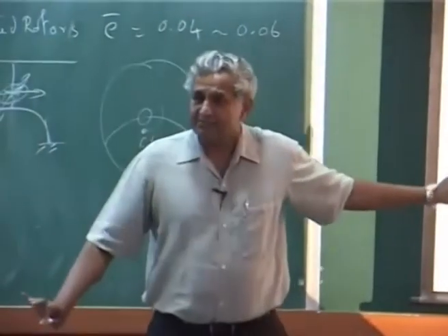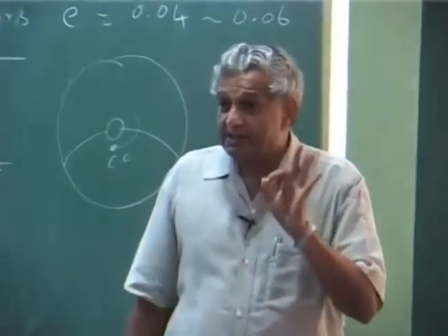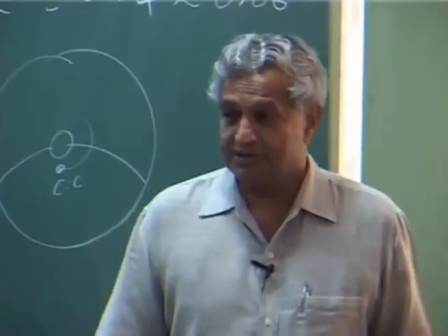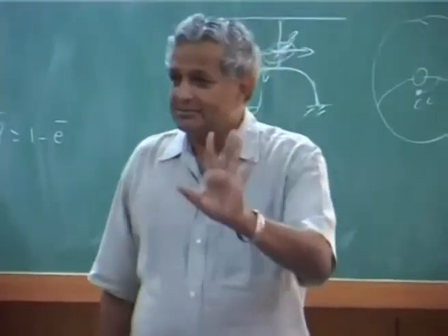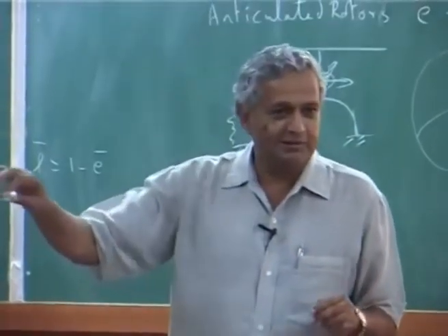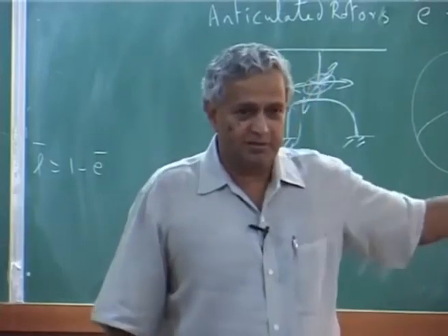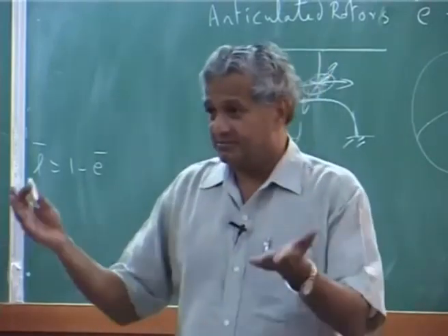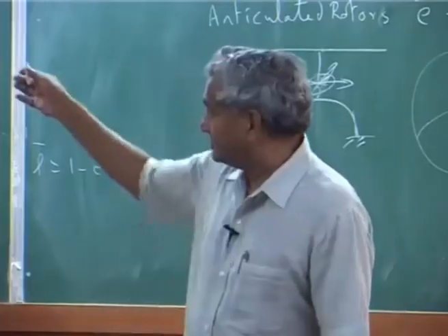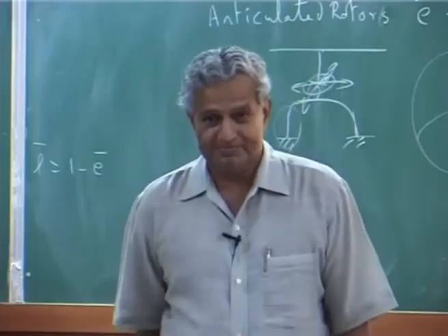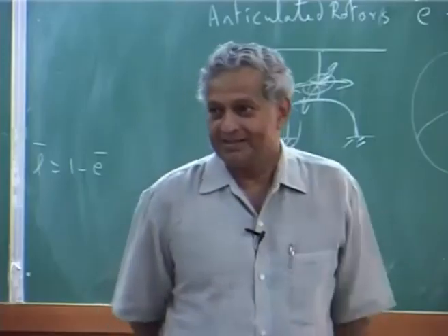Now, this much is enough for lead lag motion, isolated lag, but isolated lag is stable. Please note that if I treat only lag dynamics, it will be stable, because there is a little bit of damping that comes from the aerodynamics. Of course, if you want to put a damper, an external damper, yes, it will be stable, but the external damper is put in only to avoid this problem, flap lag instability or ground resonance problem, okay.